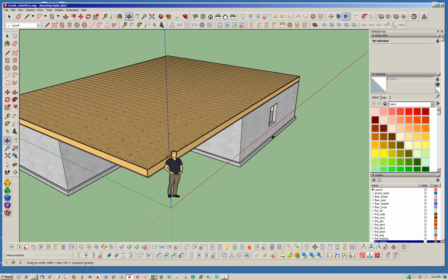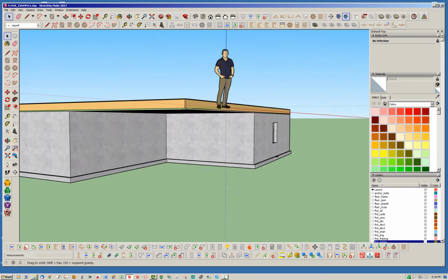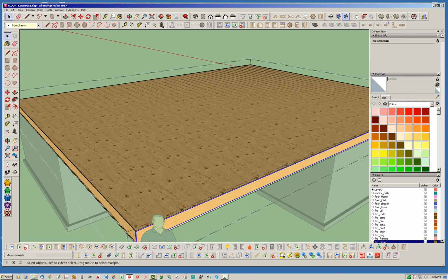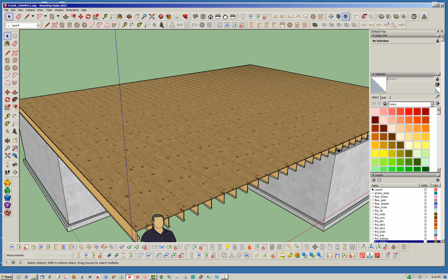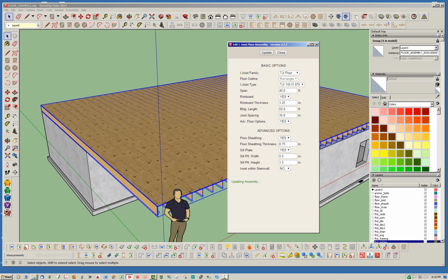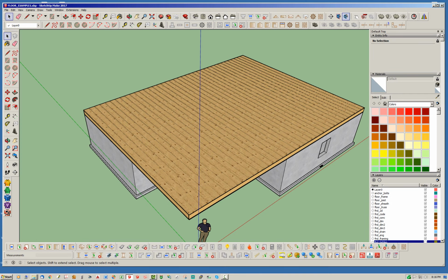But once you manually start editing this, then really you don't want to edit it again, because if you make any manual edits to this assembly, they will basically be removed. Just to demonstrate that, I'll take a click into this. Let's just say I deleted that. And then if I click edit this assembly again, and I hit update, you're going to see it's going to regenerate those members that were taken away. So anything that gets modified will be replaced if you do regen or update an assembly.